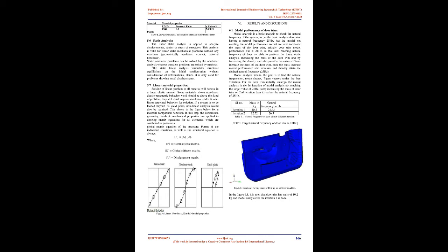5. There is no physical test in the development process of this new vehicle door product. Just using FEM to discover design problems and make targeted recommendations for improvement is very effective. It quickly guides engineers to improve product quality. This method can reduce prototype production and the number of physical tests to shorten the development cycle and reduce development investment.